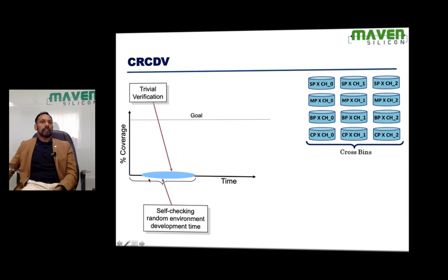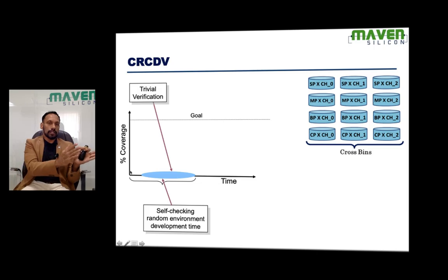Let's say it takes 1 day for a small design, but we cannot consider the time spent on test bench verification as design verification, because during this verification the coverage will be 0. We haven't verified any of the DUV features. What we are doing is verifying the test bench itself.